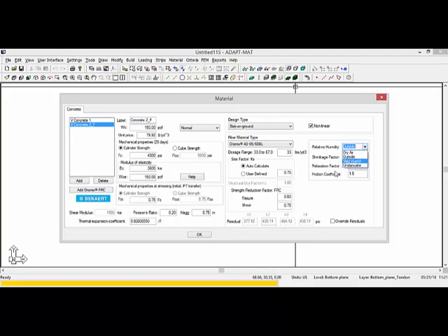Also, there's a relaxation and a friction coefficient that are required in order to determine some of the variables related to the nonlinear aspect of the design. So we'll leave these values as set, shown here. For additional information, we can reference the documentation related to fiber for Adapt Builder. Once the values have been set, we want to take note of this value FR1. This is 377 psi, and I'll go ahead and say OK.